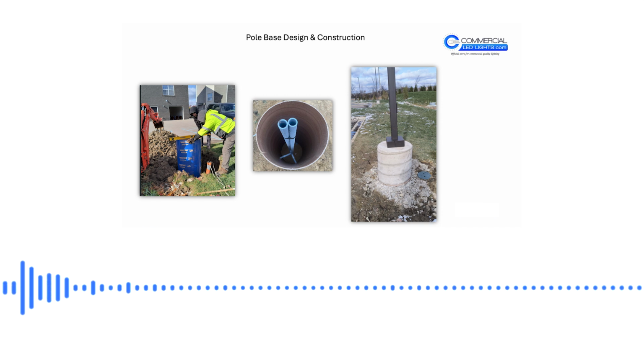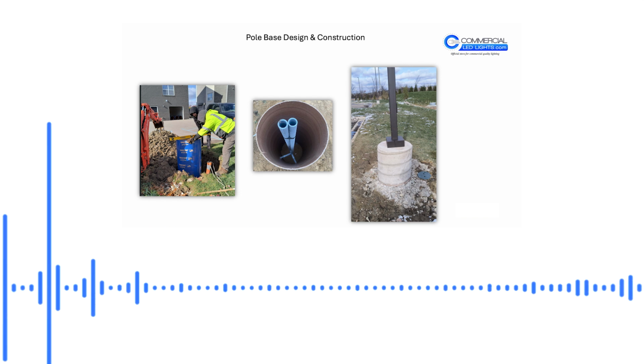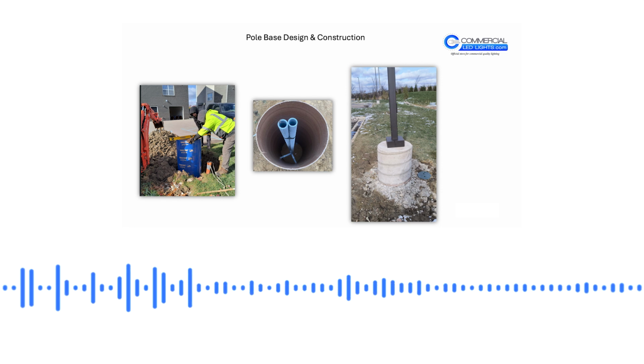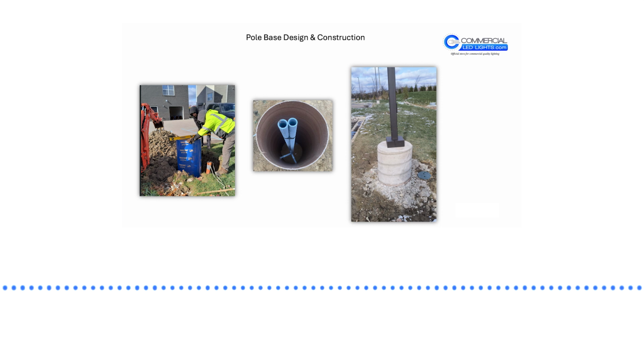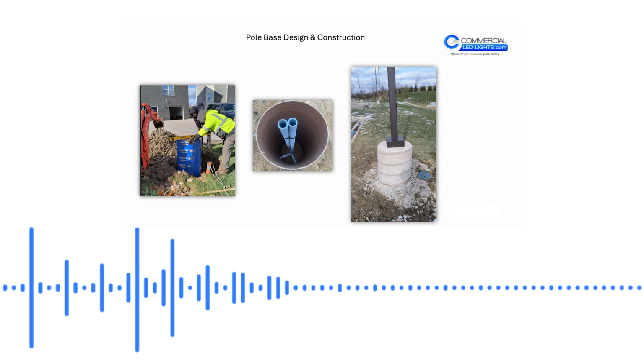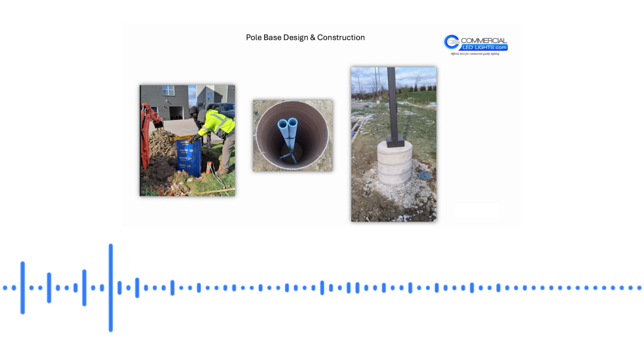There are also some other accessories, if you will, that some poles need. If there are certain types of vibration, there are dampers for those. There are specific grounding methods for the electricity that might also need to go in, and all these things need to be considered for extreme fatigue, ice loading, and even seismic requirements. So again, that's going to be out in maybe California, where we have to be aware of earthquakes. So that's another element that needs to be taken into consideration.